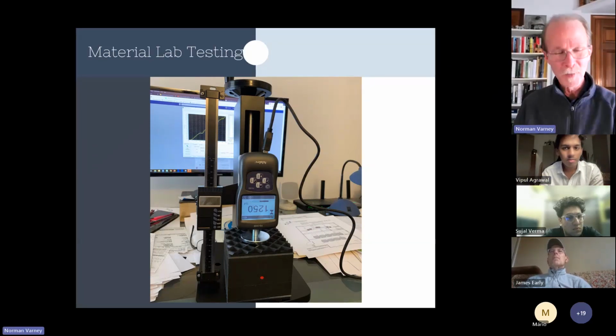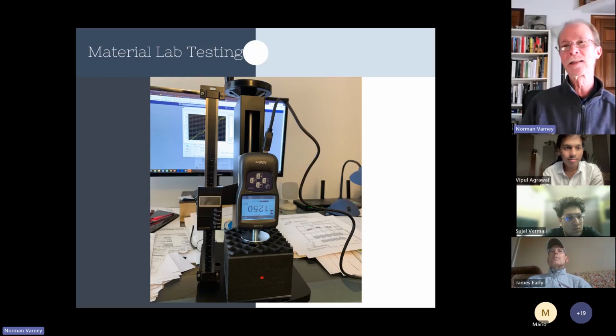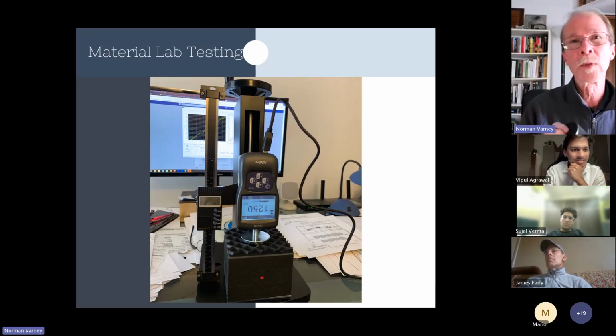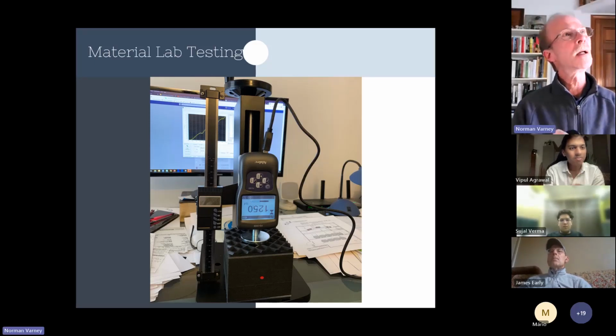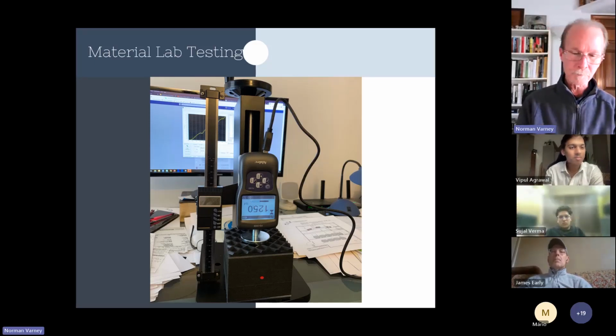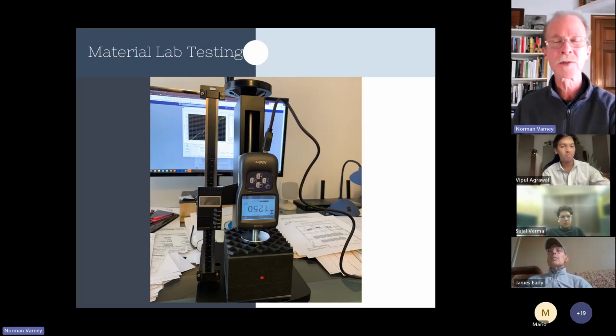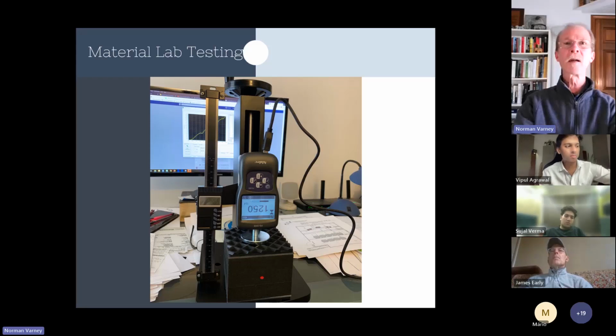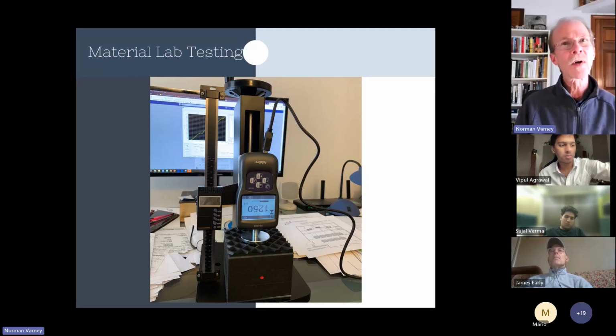That's why I wasn't planning on going into this heavy, but because this is the biggest bang for the buck. So let's explain why. Isolation of your loudspeakers. That's your source of vibration, and typically they're just resting on the structure and everything's hard fastened.